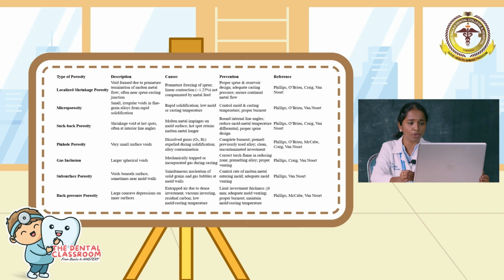Coming to the pinhole porosities, that is caused due to the dissolved gases, oxygen and hydrogen expelled during solidification, and alloy contamination can also contribute to the causes. This can be prevented by complete burnout, pre-melting previously used alloys, and clean and uncontaminated investment materials.